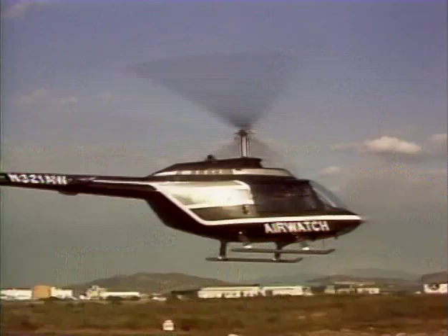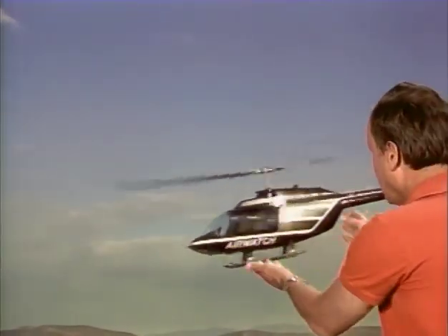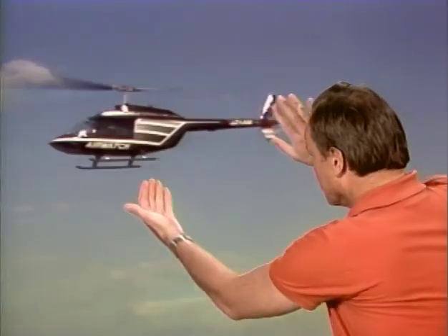Now, the tail rotor blades compensate for that torque, and they're going to ask you what happens if you have a decrease in the pitch angle of the tail rotor blades. And the answer is you have just exactly that: the tail tends to pivot in the direction of torque rotation around the main rotor axis.